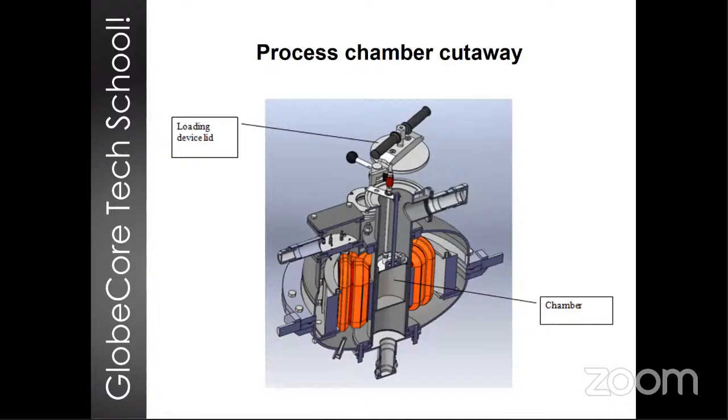Right, so the performance of the purification process largely depends on the rate of separation of the suspension into water and sludge, or rather sediment. The processing of the suspension in the process chamber of the AVS leads to an accelerated deposition of the solid phase, regardless of whether it was formed from a solution or introduced externally. This is due to the fact that solid particles in the process acquire new properties. They lose their shroud of positive and negative charged ions held by the van der Waals forces, and so they descend through the liquid much faster.